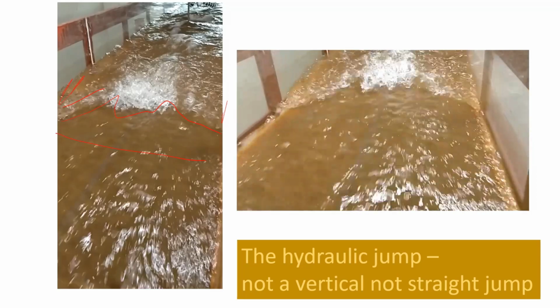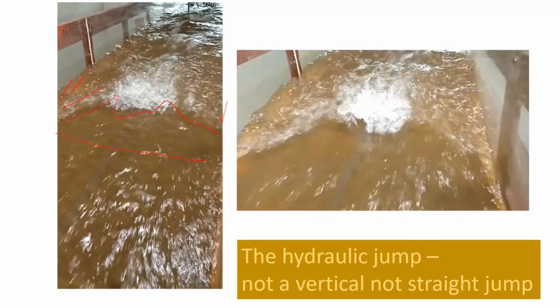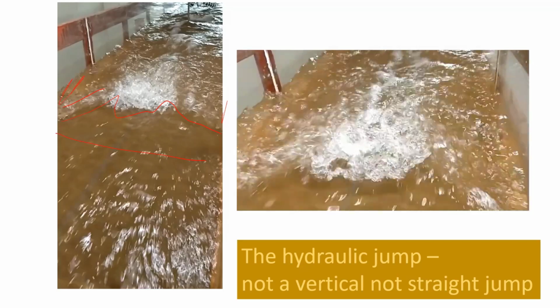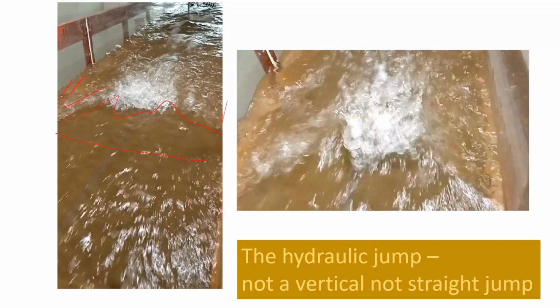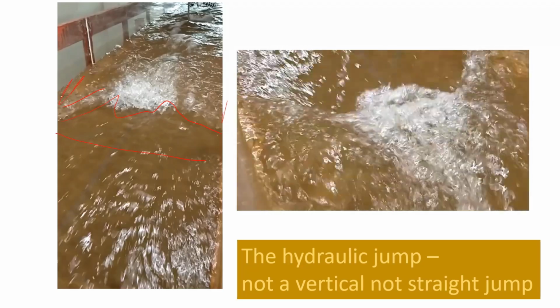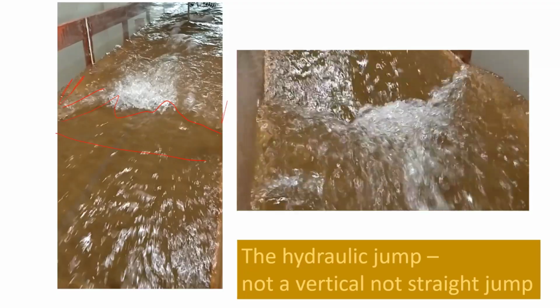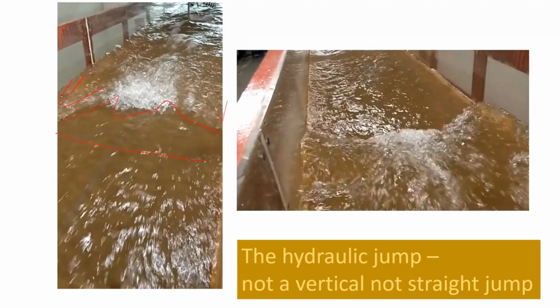So the second video here, showing something similar, slightly different angle. Hopefully you can just see it's highly turbulent in front of the jump there. That's always going to be the case. There's a lot of energy lost in the jump. Remember, we didn't analyse this with the energy equation because we found that energy was lost through this turbulence.